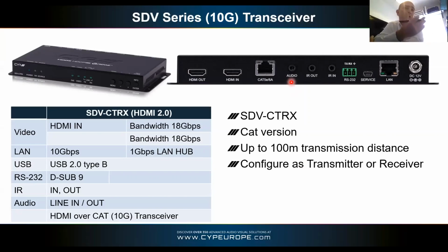So input, you just use it as a standard audio to get the audio across as a separate audio stream. But if you have it as an output, it will de-embed the audio coming in from the HDMI, if in fact that is stereo audio. So you've got dual functionality there. In the receiver, it's just fixed, but in the transmitter, you can decide which way that audio goes.